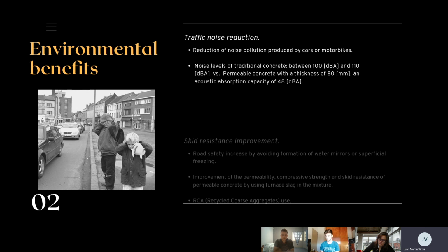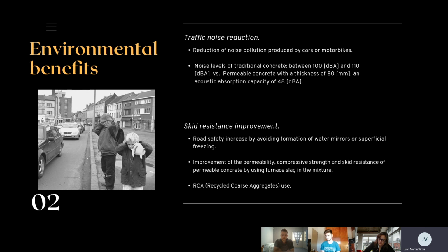The last benefit of using this concrete is skid resistance improvement. Permeable concrete has a great skid resistance, which depends on some properties such as the degree of its porosity, density, uniformity, water cement ratio, aggregate size, and its permeability.